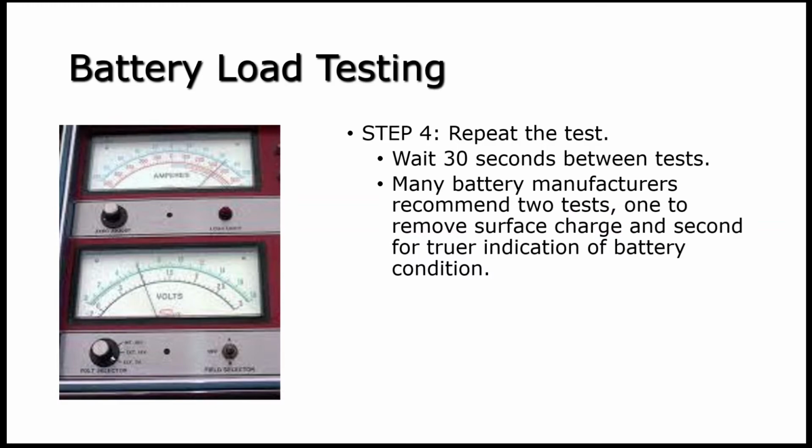So again, the manufacturers of the capacitance testers, I kind of go with them on that, simply because I listen, but sometimes they're not always right. Doesn't mean they're always right, but a lot of times they are. And being that they are the ones that built and designed the tester and know how it works, it's probably a good idea to let it sit for 10 minutes after removing a surface charge like that, and then hit it with the capacitance tester, okay?